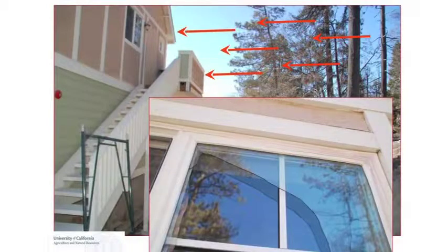Okay, so that's how it breaks. A lot of studies have shown that the most important part of your window is the glass. To the point where, with one rare exception, you could be indifferent to frame type, and buy windows based on glass. And so in that regard, dual pane is the way to go.